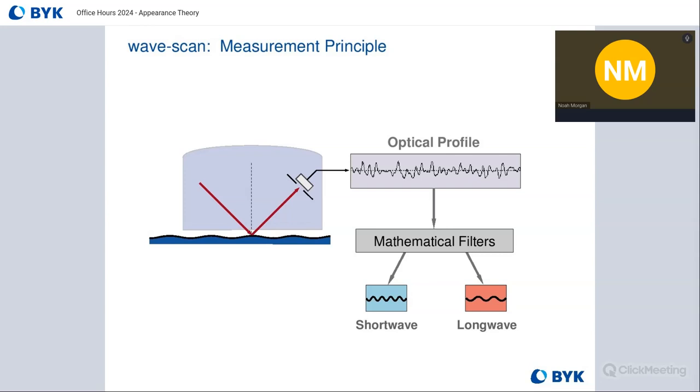As we developed better technology with coatings and instruments, we needed better ways to look at that data, so we needed to separate the short wave and the long wave into different scales. As good background information, the short wave classical range is around 0.3 to 1.2 millimeters, while the long wave is from 1.2 to 12 millimeters.